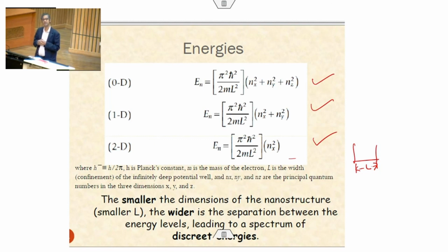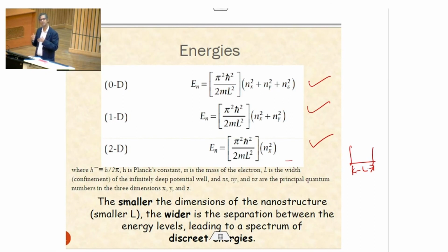Okay, what happens in 1-dimensional nanomaterials, which is very interesting. 1-dimensional nanomaterials have 2 dimensions in the nanometric domain and 1 dimension in the micrometer domain. So they can act like a phonon waveguide, similar to optical waveguides for light. For example, if you take carbon nanotubes, several investigations show that a carbon nanotube has a very high thermal conductivity along the length of the tube. That means the phonons are moving very fast along the length of the tube, just like in a waveguide.